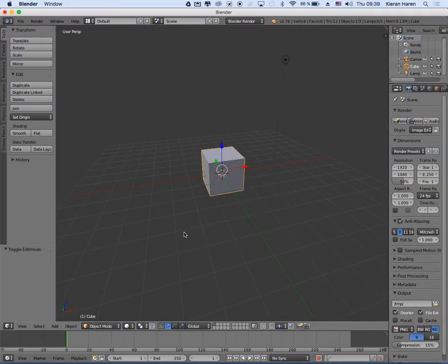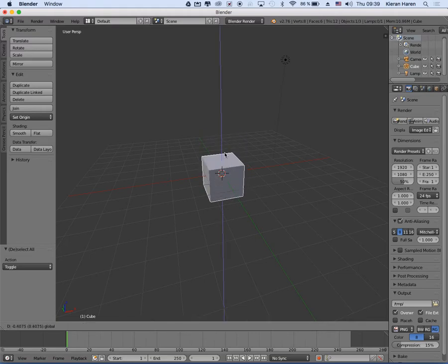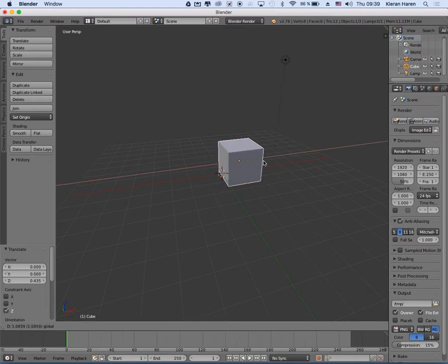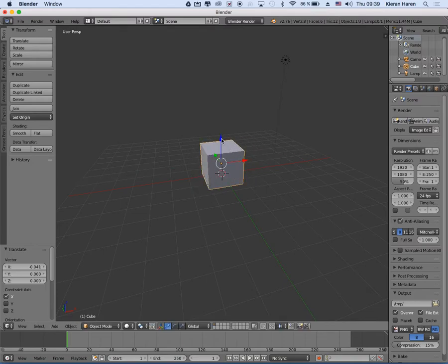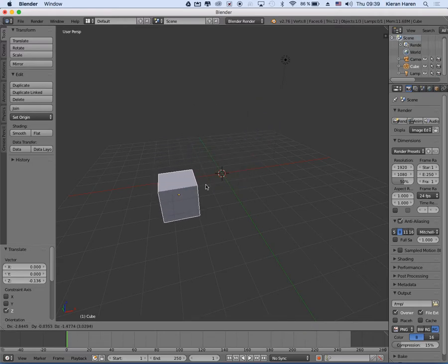We've spoken about this already. It lets you select everything or select all. Okay, select none or select all, like that. So if you want to select something in Blender, you need to right click. That's a two-finger tap on the Mac trackpad here. And then you can use the arrows to move it in the different directions, X, Y, and Z. You can also press G on your keyboard, and that grabs it and just lets you move it around.